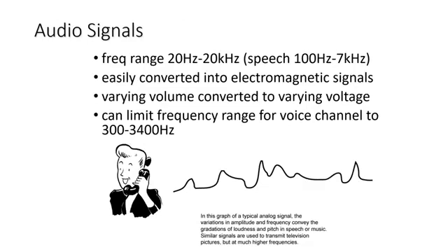The most familiar example of analog information is audio or acoustic sound wave information, for example, human speech. It is easily converted to an electromagnetic signal for transmission. All of the sound frequencies whose amplitude is measured in terms of loudness are converted into electromagnetic frequencies whose amplitude is measured in volts. The telephone handset consists of a simple mechanism for making such a conversion. In the case of voice data, the data can be represented directly by an electromagnetic signal occupying the same spectrum. The spectrum of speech is approximately 100 Hz to 7 kHz, although a much narrower bandwidth will produce acceptable voice reproduction. The standard spectrum for a voice channel is 300 to 3400 Hz.